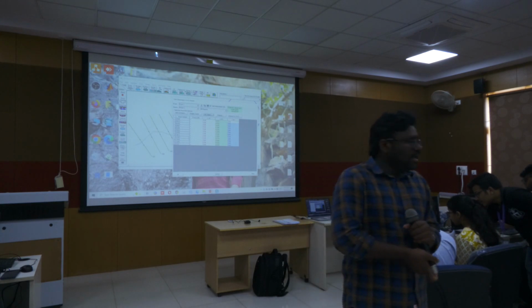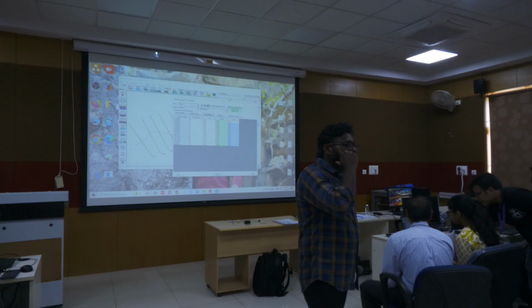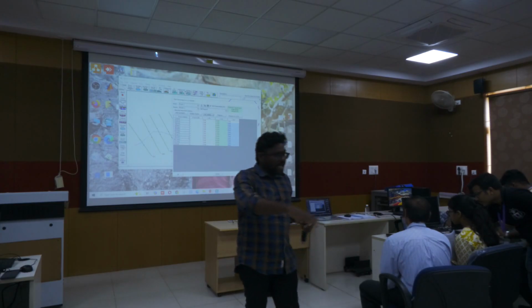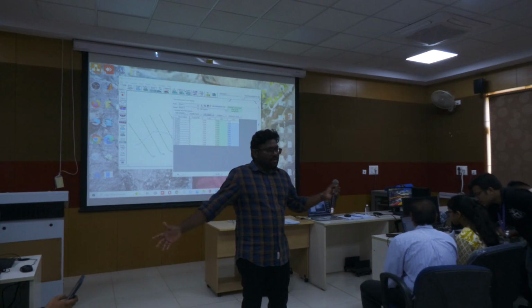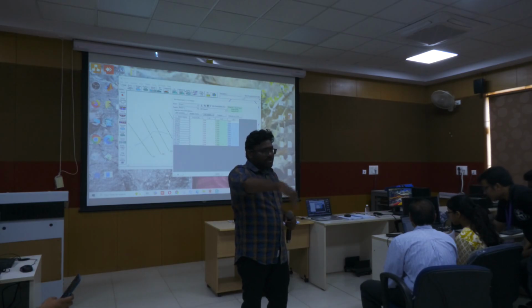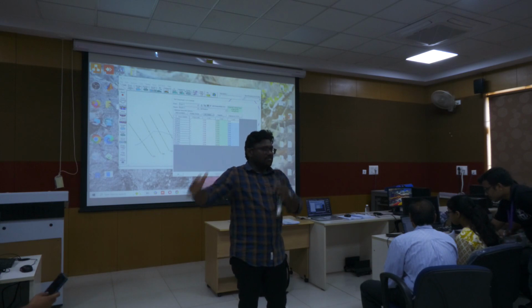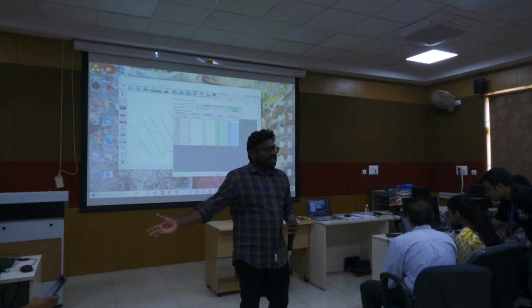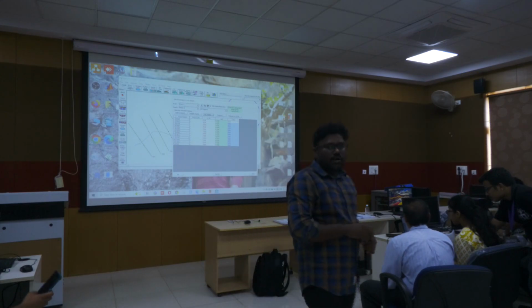So in the main channel, N has to be roughness. All the values are roughness, all the three are roughness. N2 is indicating the main channel, and the other two are banks, the left bank and right bank. We are assigning the same roughness throughout the main channel, 0.035. The banks, left and right bank, we are assigning the same roughness. Understood? Obviously, outside the main channel you have more roughness. So you have just given values like that. Okay?